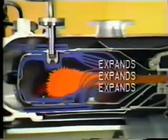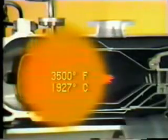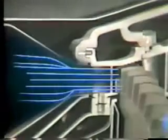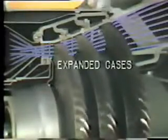Two important events occur here. The air cools the hot combustion gases before entering the turbine section, and the air is heated and rapidly expands. Without this cooling air, the combustor would be one big fireball at about 3,500 degrees Fahrenheit, and metals in the turbine section cannot tolerate such temperatures for long. Also, by using heat of combustion to rapidly expand the secondary air, a great increase in airflow occurs. Airflow that will directly turn the turbine to produce power.